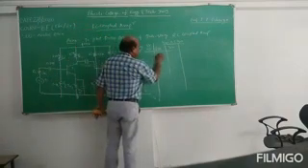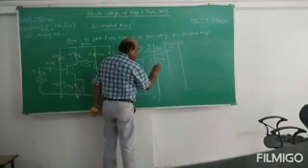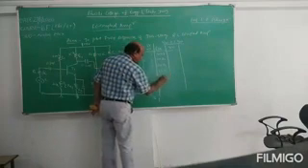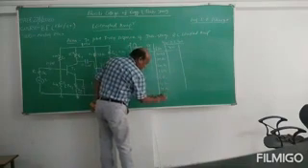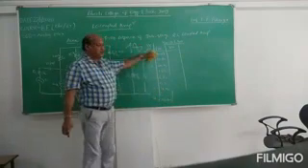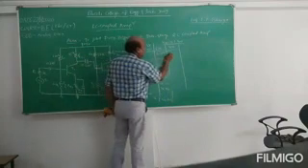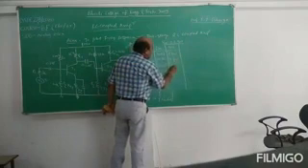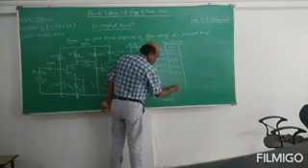Start from 50 Hz, then 100 Hz, then 200 Hz, then 1 kilohertz, then 2 kilohertz, then 10 kilohertz, then 20 kilohertz, up to let us say 100 kilohertz. Take these readings for different frequencies and measure the output at this side. Let us say this output is 0.3 volt, 0.5 volt, 0.6 volt, and so on.